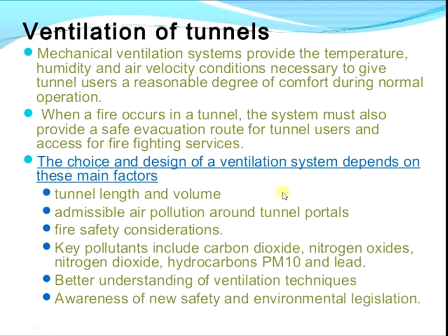The choice and design of the ventilation depends on these factors. The first important factor is the length and volume of the tunnel. Second, the admissible air pollution around the tunnel portals. Third, for safety purposes, the fire safety consideration. Next, the key pollutants include carbon dioxide, nitrogen oxides, hydrocarbons, PM10 and lead. And next, better understanding of the ventilation techniques, and awareness of the new safety and environmental legislation.